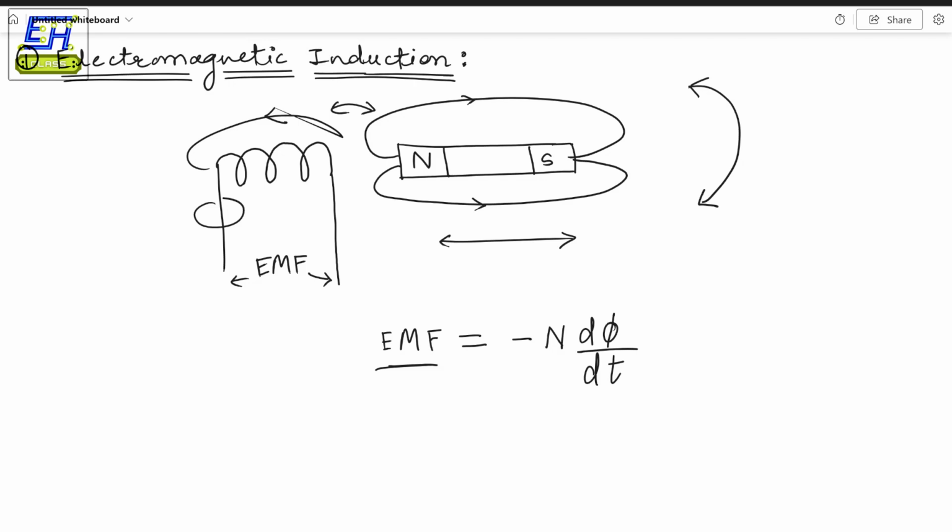This is where you need to burn real energy, whenever you have the generator. If you have nothing connected across the terminals of the electrical generator, you won't see any physical impedance while you turn the shaft. But when you connect the load, because this non-zero current is now flowing and creating its own internal magnetic field, which conflicts with the external magnetic field, real work has to be done.